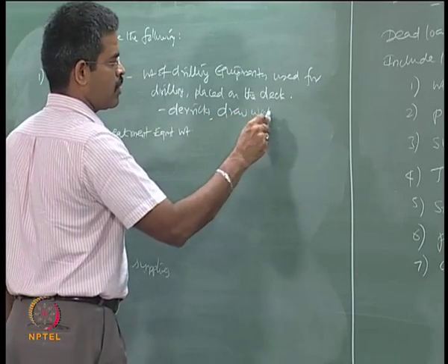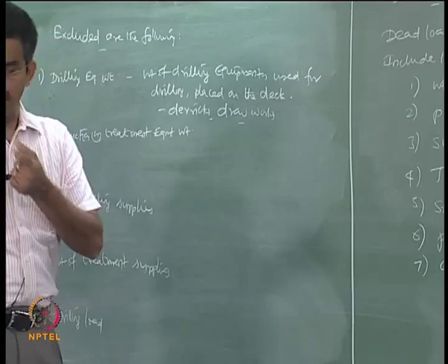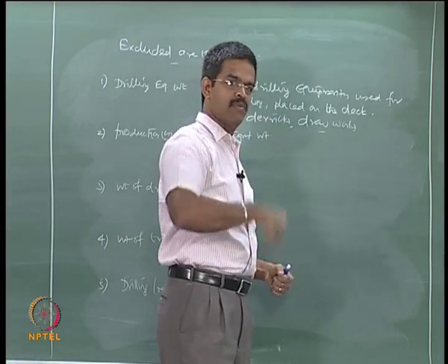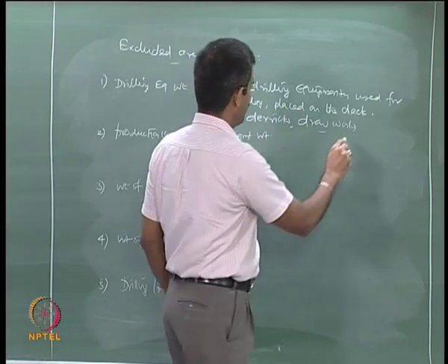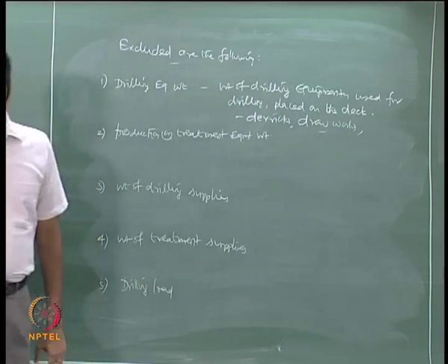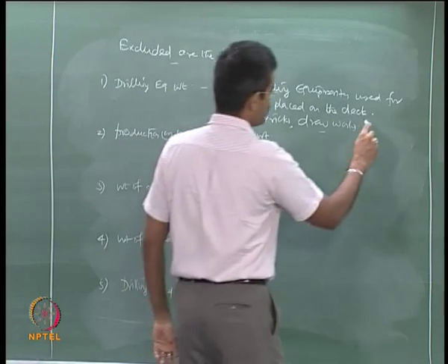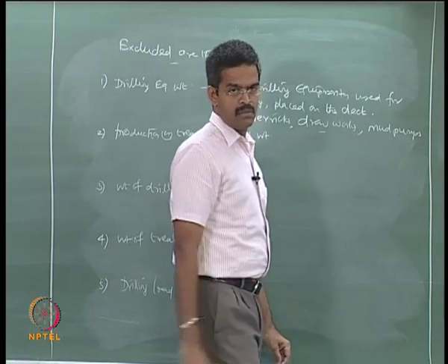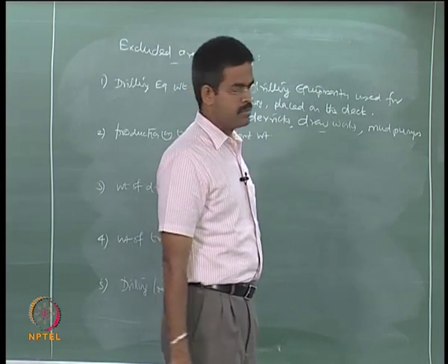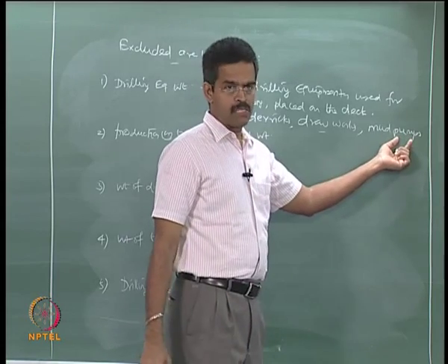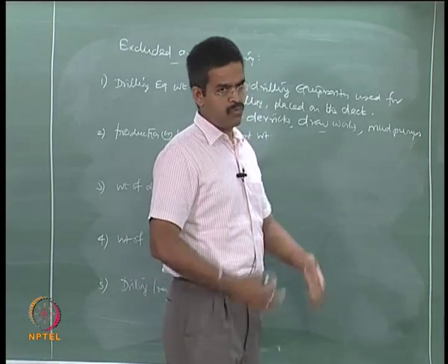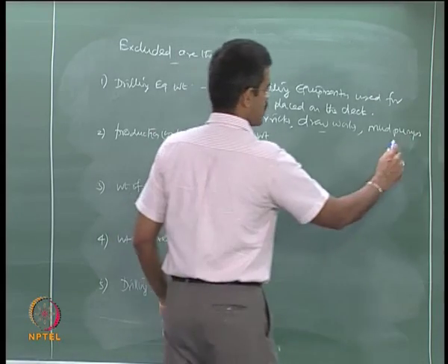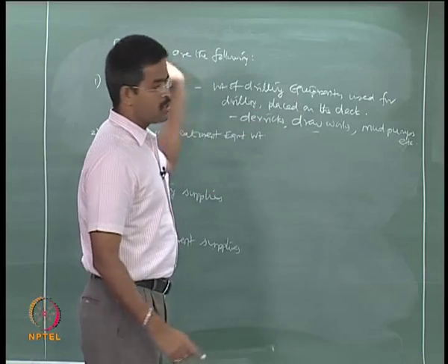You understand what is a drawwork? Drawworks are those mechanical equipments which are used for drawing oil or sucking oil from the seabed. They are called drawworks in general. Mud pumps, we all know why mud pumps are required. Drilling mud is a very important component in drilling operation, and we need to pump these muds because they have a very high specific gravity, they do not flow automatically, we have got to pump them. So, mud pumps, etc. They are all excluded. Okay.